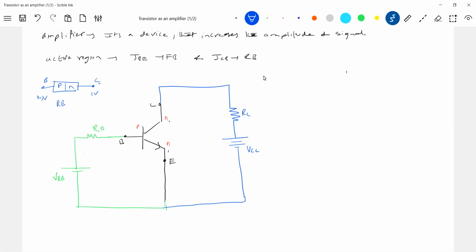The same thing is happening. I'll see that the VCC will be greater than VBB. This will be of order 0 to 2 volt. This will be of order 0 to 20 volt. So definitely the collector base junction will be reverse bias. Like that, the values of RC, VCC, VBB, RB are so adjusted that first these conditions will be satisfied. Got the idea? Already in the morning we have discussed the same thing, I'm continuing here.